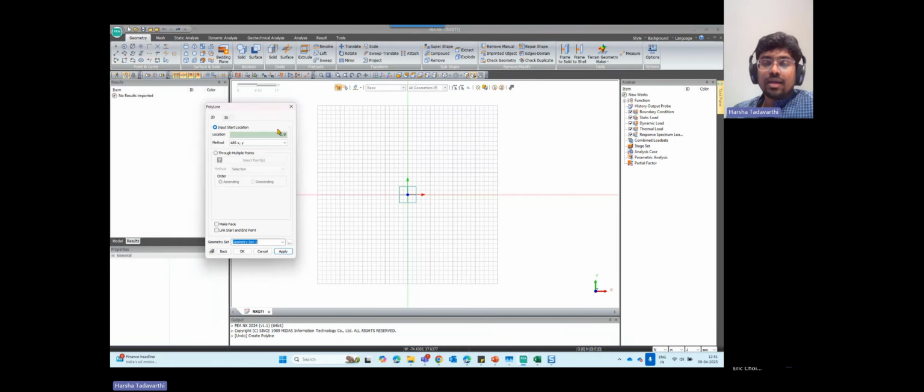Now we are going to place the dam at the center. The heel of the dam will be at the origin, okay? And then from the origin, it will be 30 meters high with a 5-meter width at the top, and then 3 meters downwards, and then the downstream slope, covering the entire width of the dam of 18.5 meters.